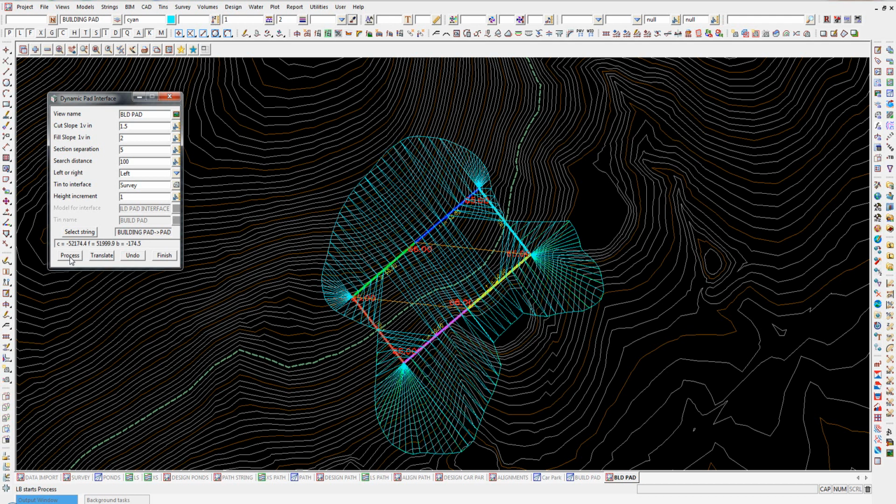So as I said, each time this is lifting that pad by a certain amount, and I might be happy with that. Let's see what happens if I go to 0.05 and process that. I've actually gone too far on that, so change that back to a -0.5. Process again, and there we are. I've got about 174 cubes of dirt left over from my cut to my fill, so that gives us a little small excess which we'd probably want.